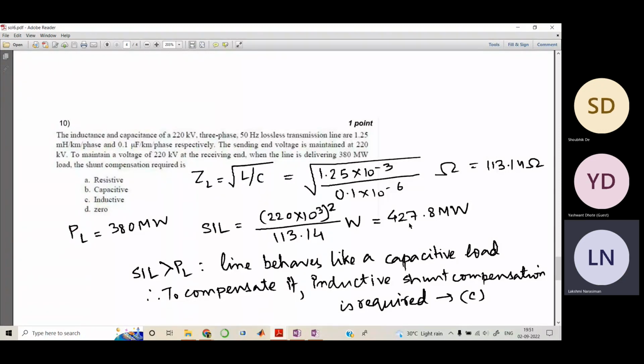Okay, because whatever derivations and problems I have seen are all pi model related, and nothing is for a short line or a long line. The derivation gives the final formula, the admittance matrix, everything, and the y11, y12 and their signs totally depend on the model itself. It's applicable only for the pi model. If I change that to another model, the signs may change, the values may change, and the matrix values would also change. So we are only doing it for the pi model. That is what I was thinking.